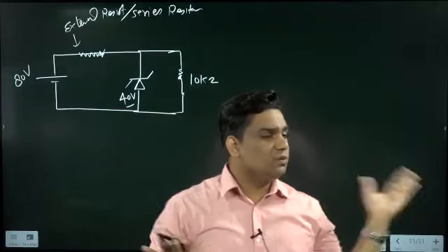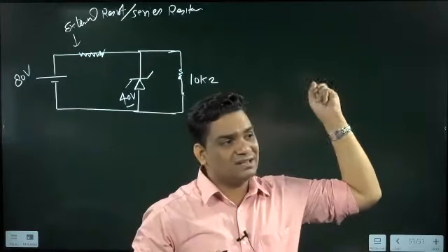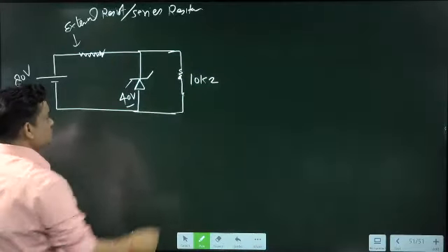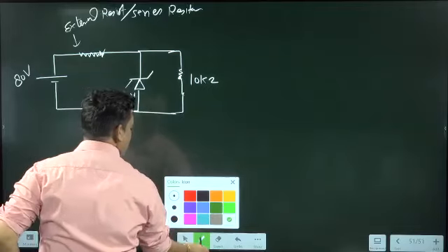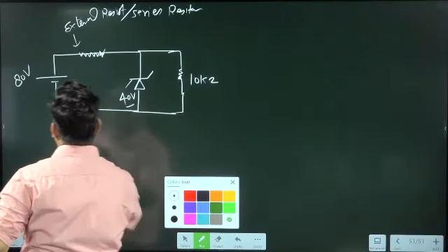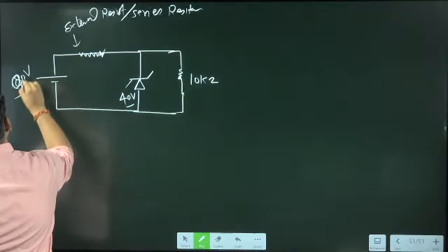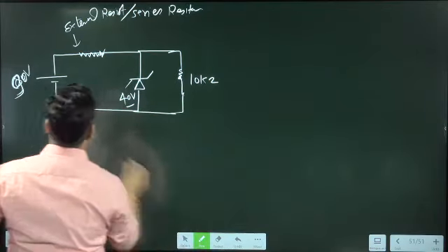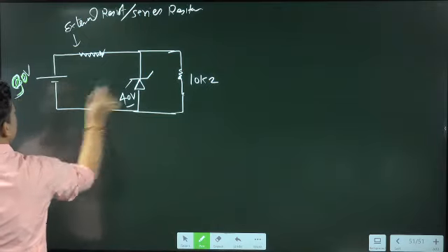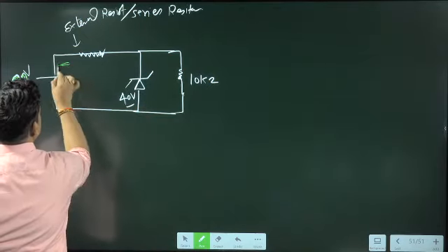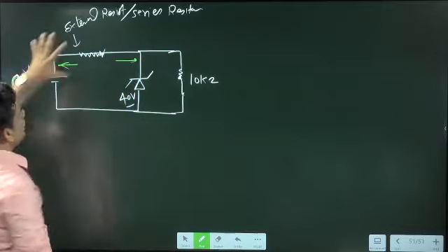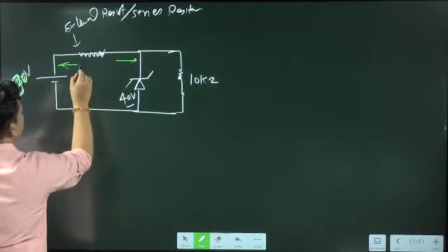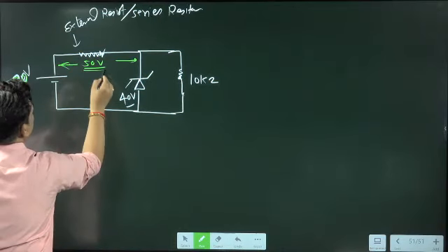If you want to vary the current, then by varying this resistance we can change the current also. So in this question, suppose the supply is 90, I can say 90 now, okay, 100, anything can be here. Out of 90, the Zener will take 40. Extra voltage is handled by the series resistance, so this is going to take 50 volt all the time.